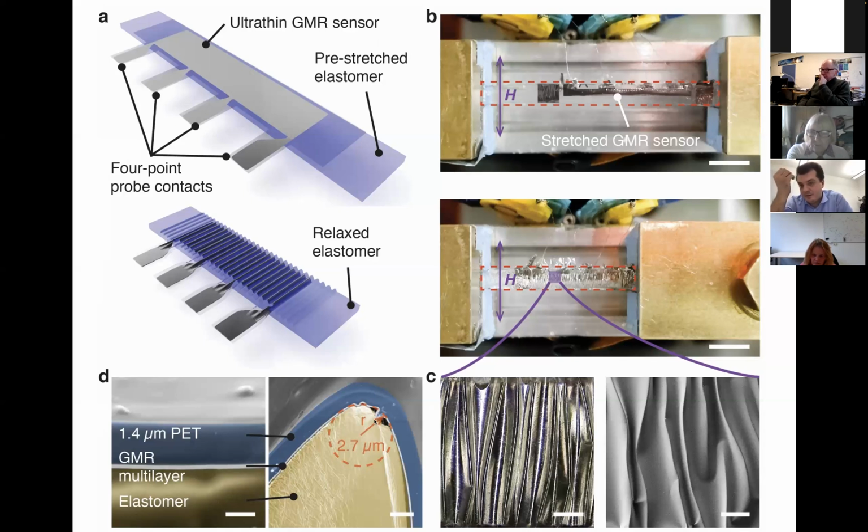So which friction effects are there on a nanoscale, right? Macroscopically, we probably don't see it, but what is a nanoscale friction effect? How does it pin the domain walls there on these bends? This is something which contributes to the sensitivity of the sensors. Yes, it's nanoscale, but curvatures here are also not so far off, yeah? And therefore, surprising, yes, but even for these large area applications, you need to understand nanoscale magnetism.